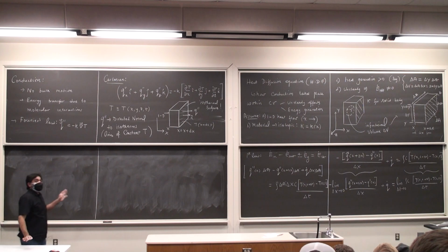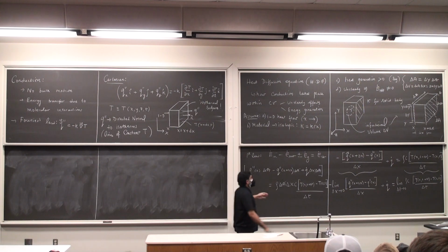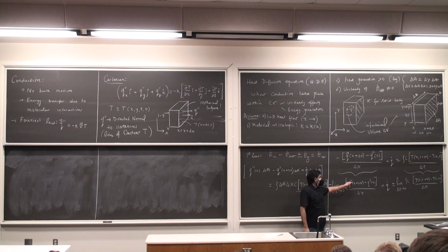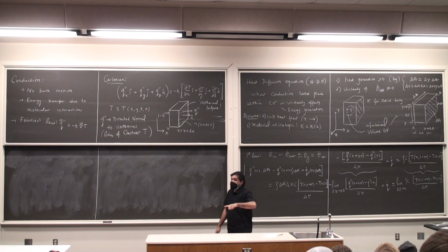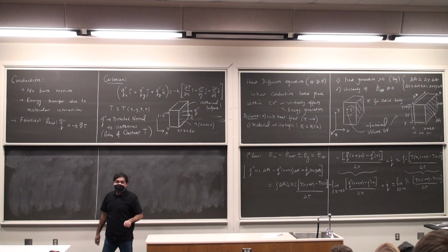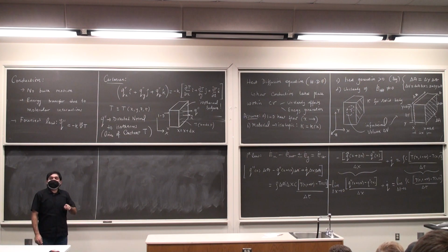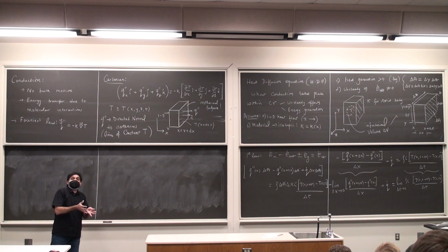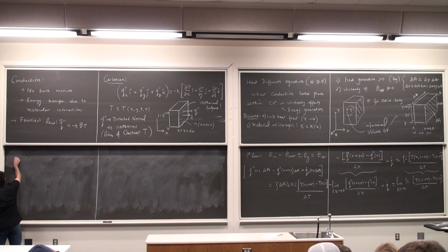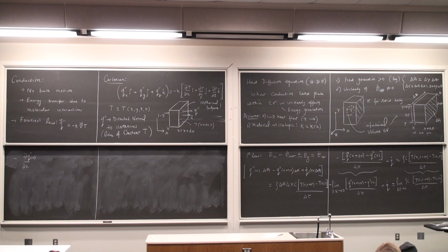Left hand side, remember there is a negative sign, but this first big term becomes the partial derivative of q double prime with respect to X. Why is it a partial derivative? Because q is a function of temperature. Temperature is a multivariate quantity. It's a function of both space and time. So I can only talk about partial derivatives because this is a derivative with respect to space. So on the left hand side I have minus dq double prime by dx as a function of x. Don't forget the quantity k, which I forgot here. Oh, well, not yet.